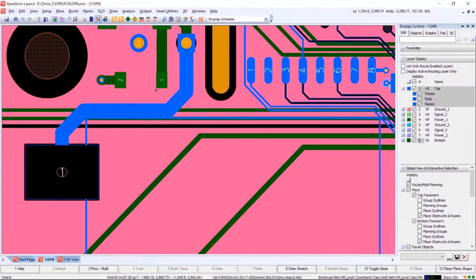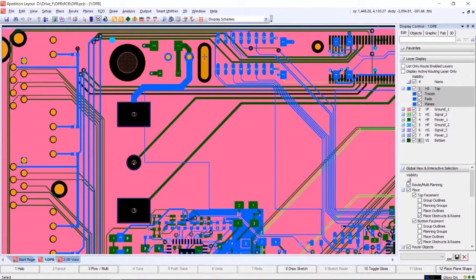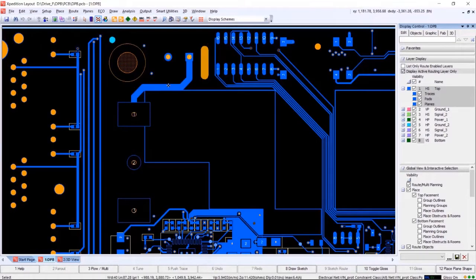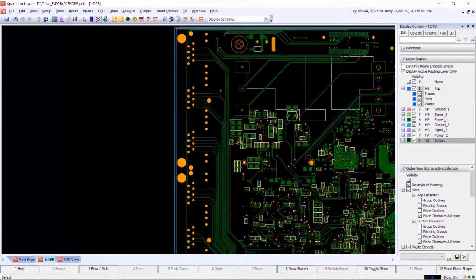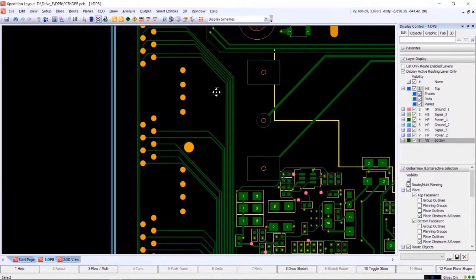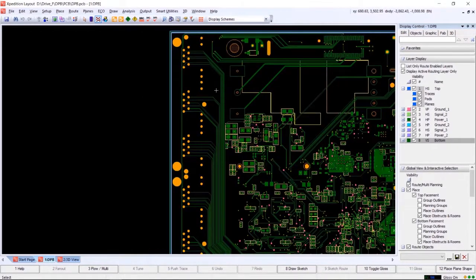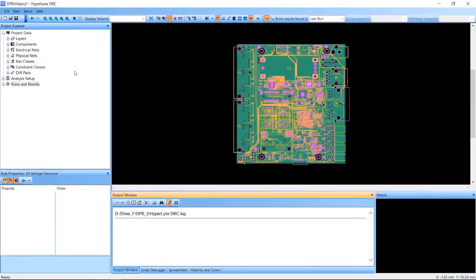For this example, I will use that 200 volt aggressor net with that cutout in between. Here we're seeing the top side of the board only from the pictures we talked about earlier in our webinar. You can see the victim net there on the top side. And then I'll switch to the bottom side of the board and show the connecting floating metal that we found in that second use case